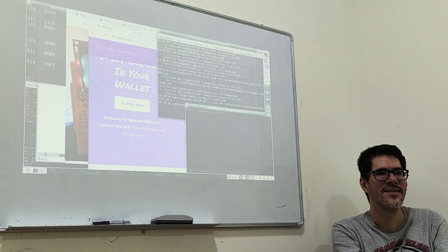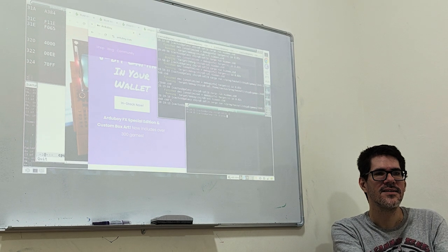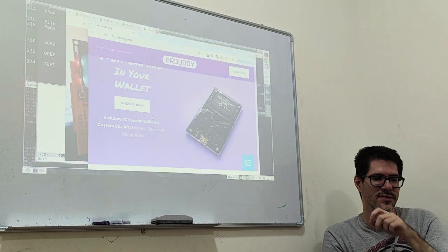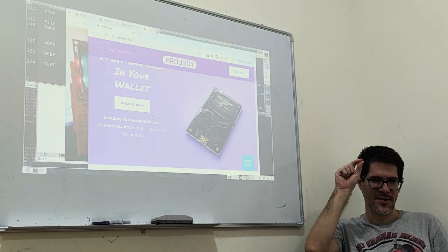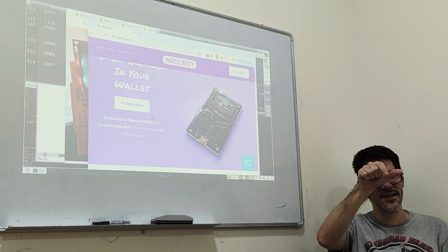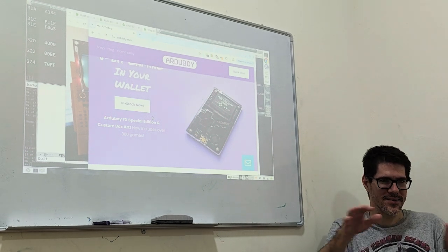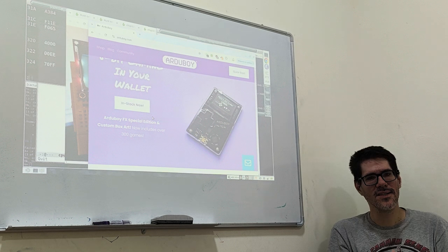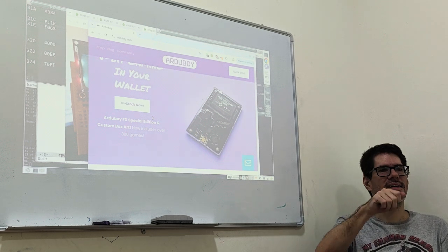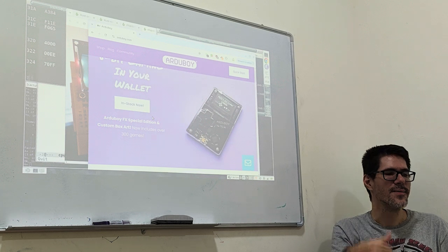So just one question, when you wait for the key press, is it a busy loop or a blocking wait? So like I said, you have both. So you have an instruction that says wait for the next key press, and once it's done, write the index of that key into this register. So that one will wait. That one is a single thing. But then you have another instruction which says, is key 3 pressed? Then if yes, then jump, otherwise continue.